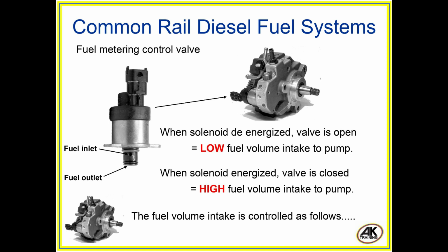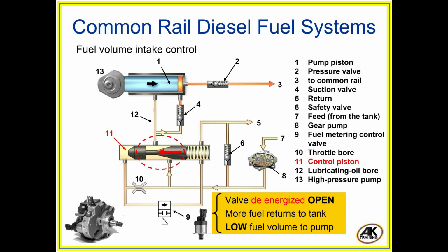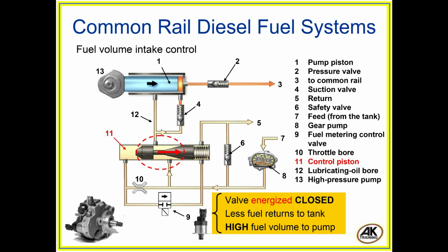The fuel volume intake is controlled as follows. Valve is de-energized so it opens, causing more fuel to return back to the tank, in effect causing low fuel volume to pump. When the valve is energized/closed, which causes less fuel returning to tank, in effect causing a high fuel volume to pump.